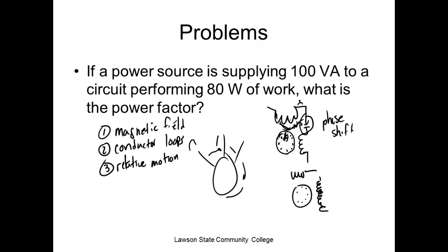So what you're saying is you could theoretically, I mean, it wouldn't be efficient, but you could theoretically run a three-phase on single phase. Well, if it's running, it would run, but it would burn itself up. We call it single phasing because the other two windings are going to try to develop the horsepower. So if you got a 30 horsepower motor, it's going to try to develop 30 horsepower. If you lose one of your phases, then the other two windings are going to try to make up the difference, which means they're going to get real hot if you don't have anything in there to sense that. And we'll talk about that later on.